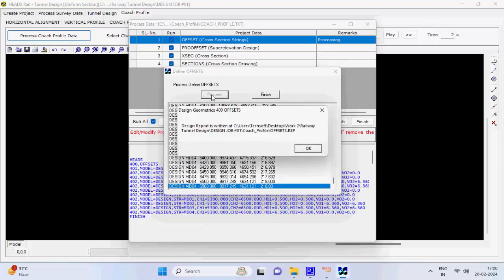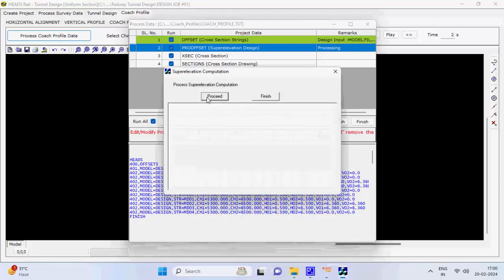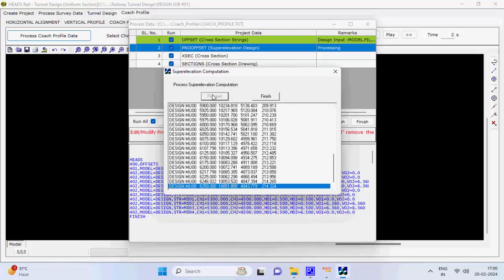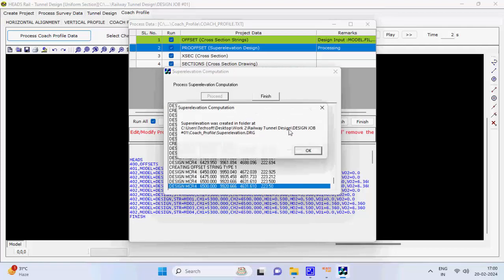Step 195. As all the processes finish, the message comes. Click on button Finish OK as shown. Step 196. Step 197. The next process starts. Now the window in tab page has the cross sections in display. Click on button Proceed. By selecting a Chainage, we can see the cross section at the particular Chainage. As the process finishes, the message comes. Click on OK.